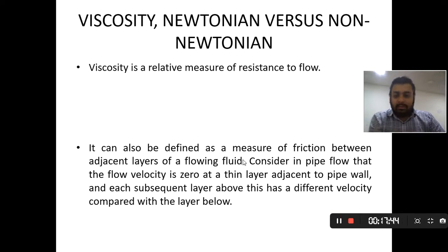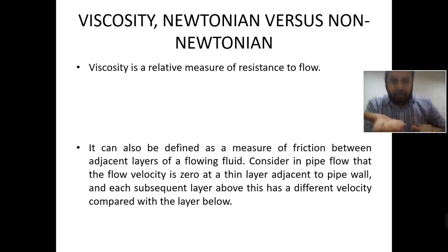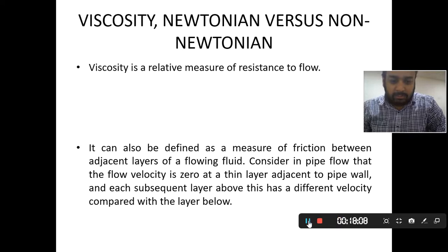For example, this is the flow of fluid, and at the same time you have another layer of fluid. So when they are moving ahead, they are actually rubbing each other. And I will show you in a video also that if the viscosity is very high, then you need more pumping pressure, you need more energy to transport it, and it will increase the operating cost of the product. So I will now show you how the viscosity is affecting.